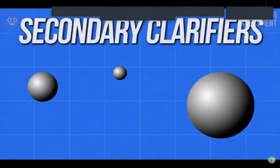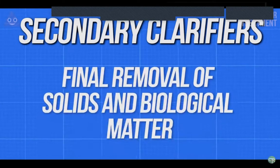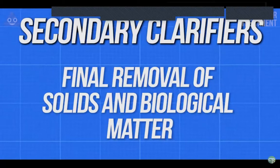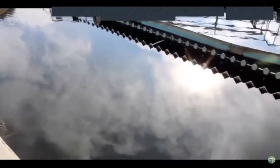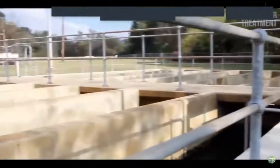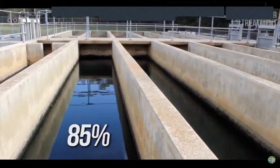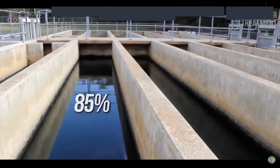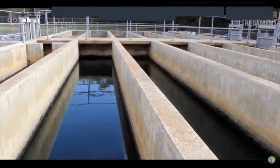Further settling of larger particles is also accomplished in these basins, as it is the final step of the process that will remove solids and larger biological matter. Water flows out of secondary clarifiers over a nearly identical weir wall to the primary clarifiers and moves on to the disinfection process. At this point, 85% of all organic matter is removed from the water, and the effluent should be safe to drink in most cases, although you probably wouldn't want to.